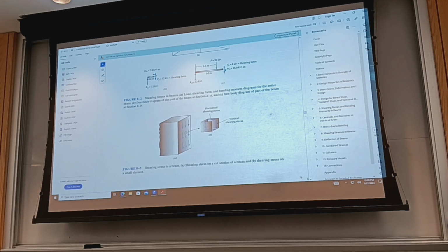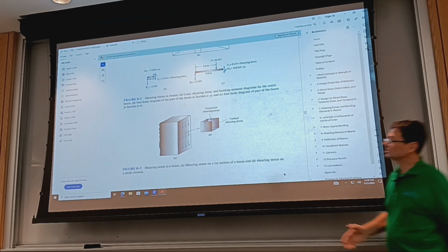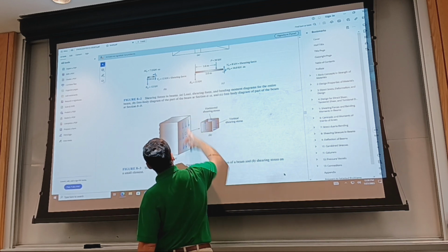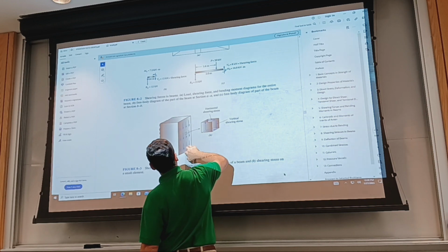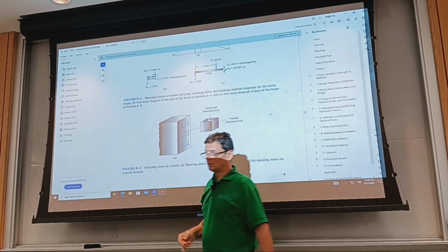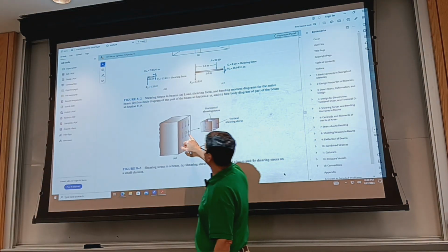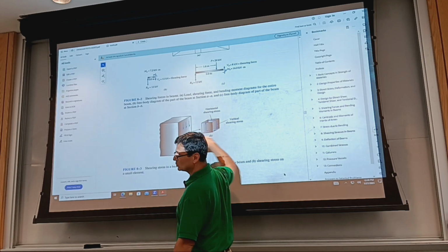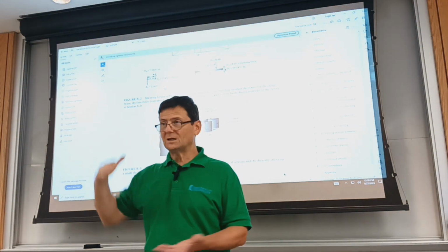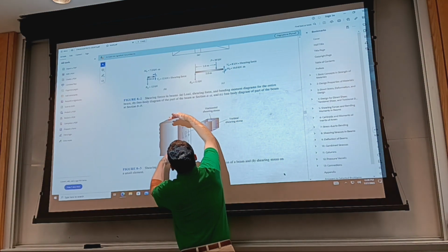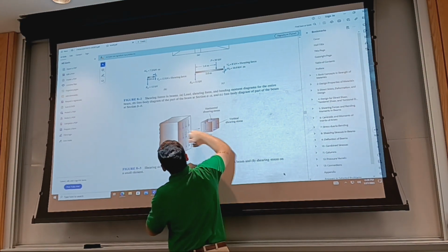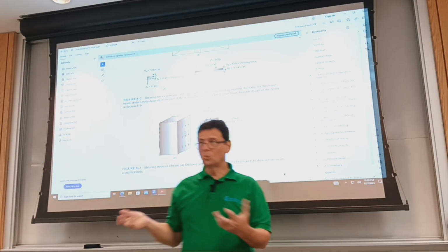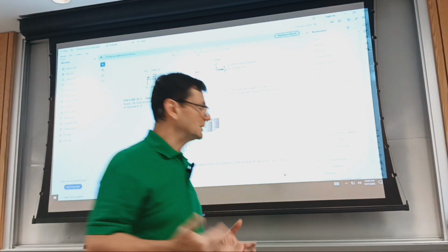And that's the way the stress element looks. We'll see that the shear stress due to the shearing force varies. Of course, it has to be zero on top. And in most cases, which is fortunate, the maximum shear stress is on the middle plane, or rather the centroidal plane of the beam. Why is that good? Because we have maximum bending stresses on the outer skins and maximum shear stress elsewhere, away and in the middle, meaning they don't get combined, which again is a good thing.